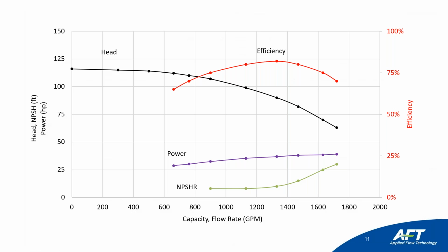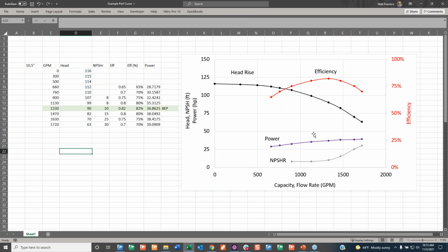So this is that same curve digitized. What I did was I took random points on the curve and made my own curve so that I can save this as an Excel file to use for future reference. And I recommend this so you can keep all your pump curves as CSVs or just Excels if you want to do your own graphing. Graphing is easy in Excel, that's why it's good. But you can also copy and paste things from Fathom and Excel interchangeably, so it's useful.